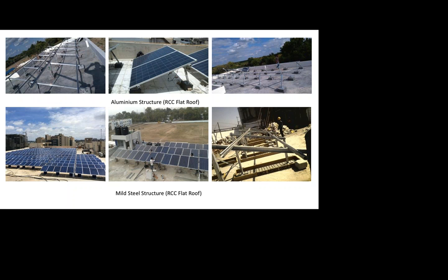As a package, it will cost you pretty less. You save essentially on the services, shifting, unloading, handling, installation, all of that part. On the supply side, they balance out each other on the tonnage, on the kgs required. So the price might be double, but the requirement is half. That is how aluminium ballast is placed against MS in situ.